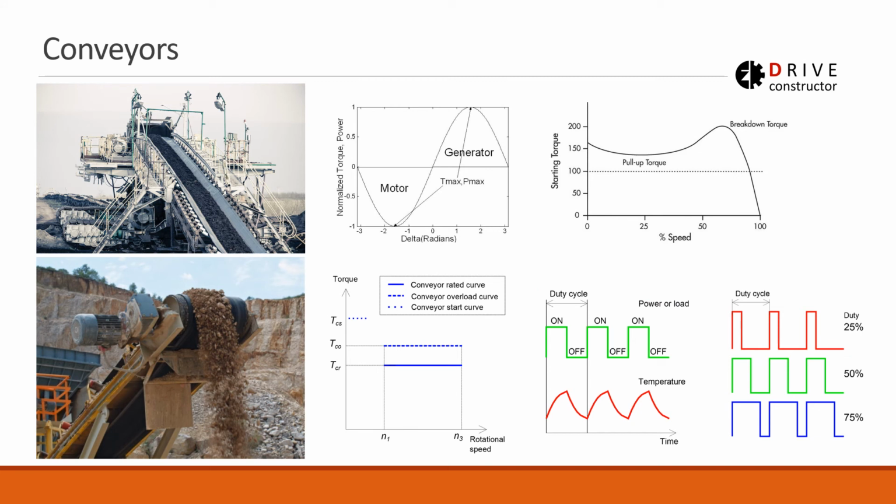Now a bit about hardcore industrial applications. So you see from the pictures the conveyors and the respective drives for the conveyors. Quite extreme things, quite harsh environment. It's a lot of dust and mud and water and whatever. So the components of the system should be really chosen with the right protection degree and with the right ability to withstand vibrations and shocks and so on. So what is typical for conveyors? It is overloads, quite high overloads. So here we see that the overload can be like 50% and even like a double overload.